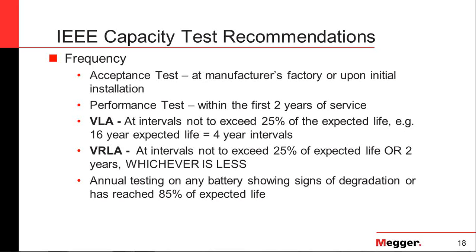Especially for us, our bite testers actually do that measurement for you, both the bite 3 and the bite 2. One with the CT clamp, one by going onto one of the straps and just measuring it. But generally speaking, what you need is an AC ammeter and some sort of clamp or some sort of way to get into the circuit or into the series path of the battery string.